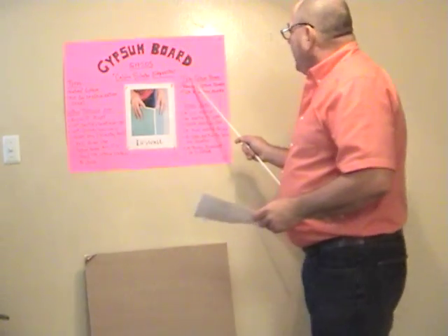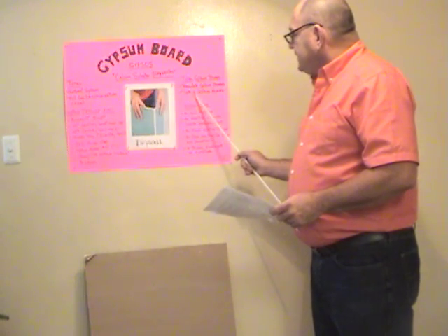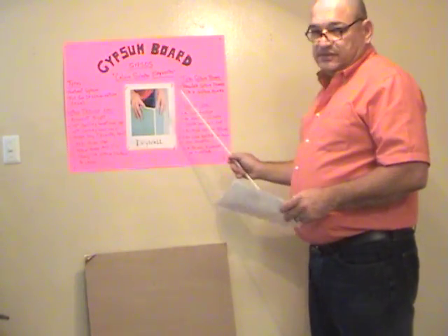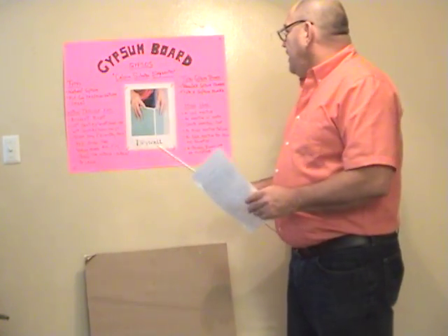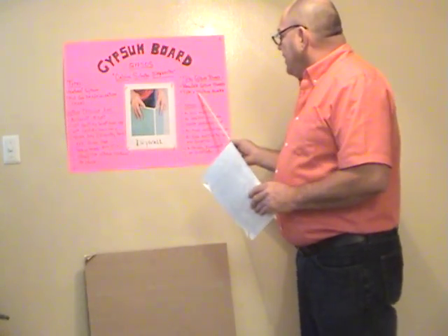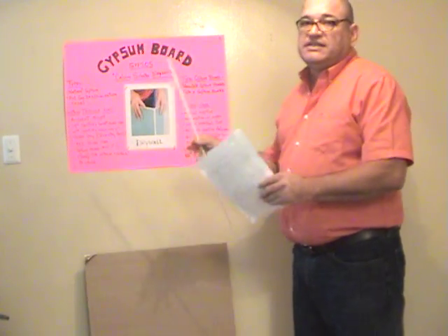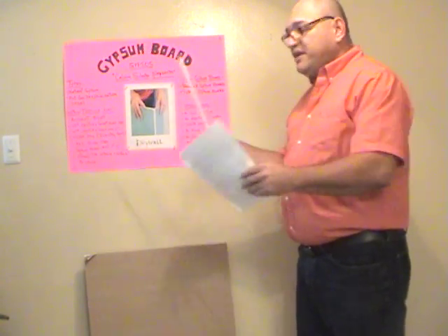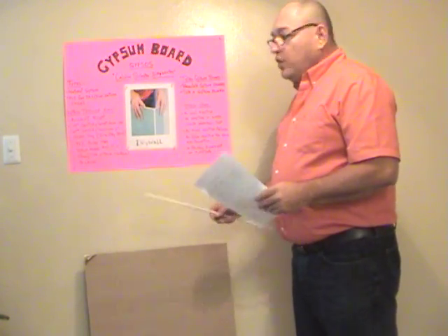We have two types of gypsum board: regular gypsum board and type X gypsum board. Regular gypsum board has normal fire resistance, and type X has some additives that increase the fire resistance in the core.